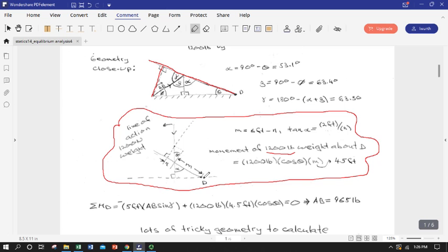So this is one using this assembly of triangles. And this one schematic, this is an example of how you can do this geometrically. And this is basically just using some trig and basic geometry to find our perpendicular offset distance, or at least a line with a known angle, so we can get a perpendicular offset.